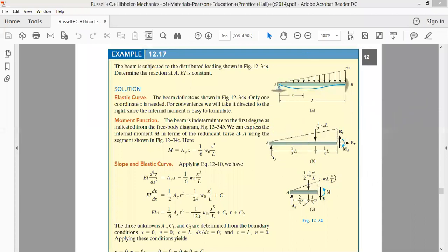So as far as this concentrated load is concerned, at the section we had taken at a distance x, we have said the shear force is V and the bending moment is M. Before taking moments, we can write the equation of equilibrium for forces.